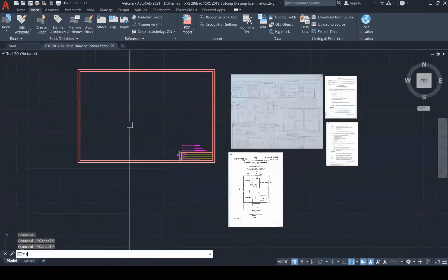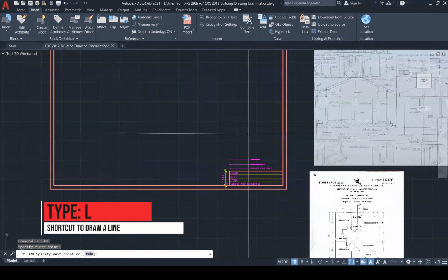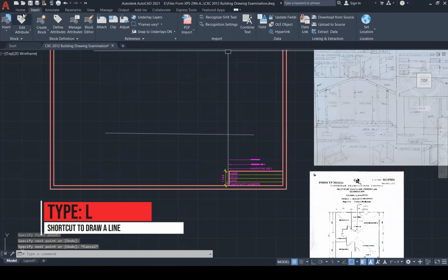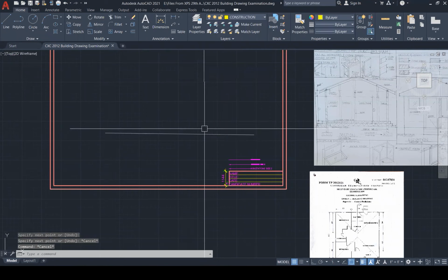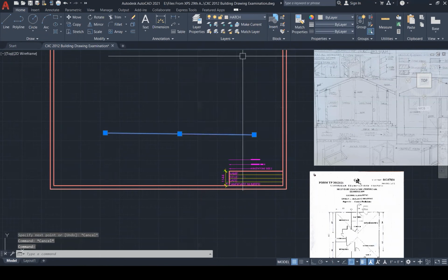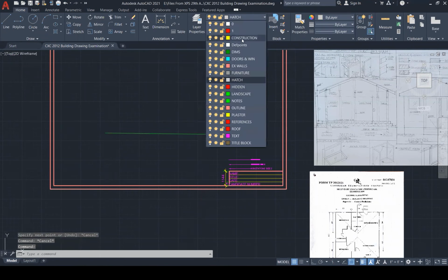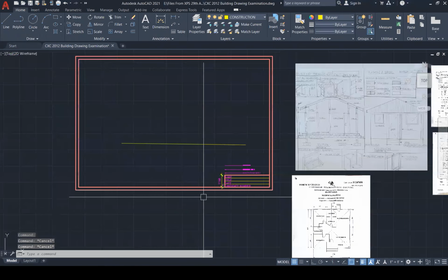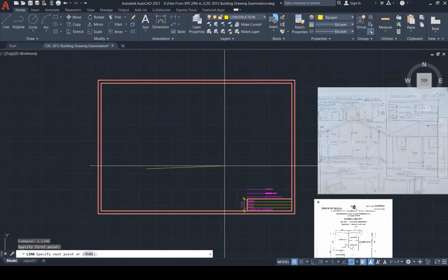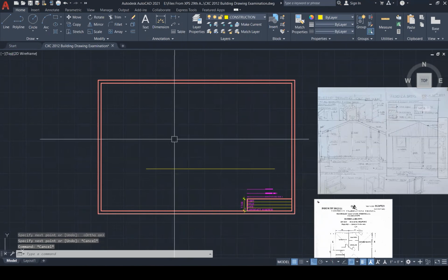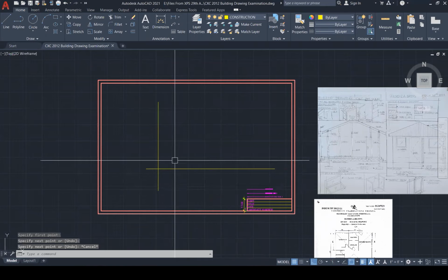All right. So let's go alpha line, and I pull this across. I'm in the hatch layer. I wish to be in a construction layer. This doesn't look straight. Alpha line, put on my ortho, and that's it. Set this up here, and that's good.